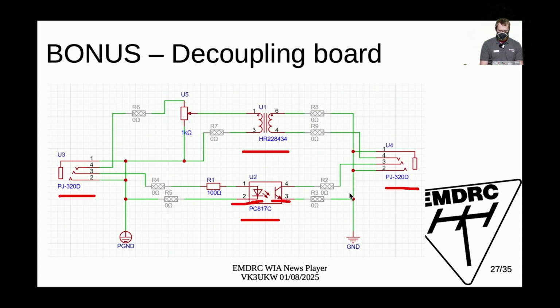That's great, because on our audio interface on the left side we've got a GPIO pin that we can set to high or low, and on this side we've got the PTT circuit in the radio that wants an active low signal. So the signal goes high on the left side and turns into a low signal on the right side, so you've got your inversion there out of the box.